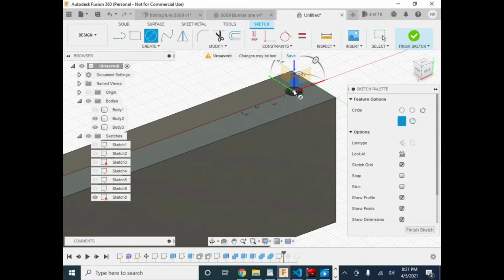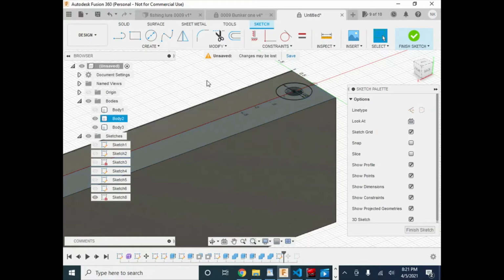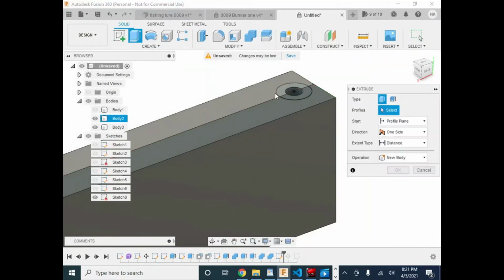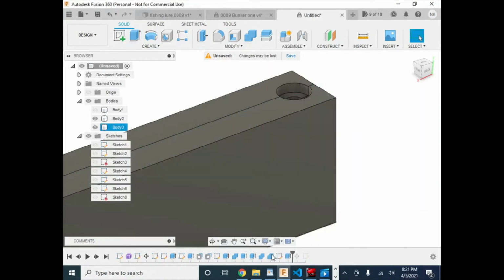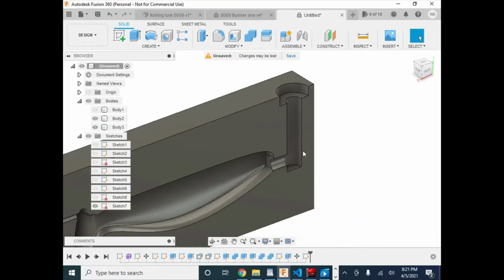We'll pick the center of the hole, and let's say we have a 1-inch diameter port. That's where I would do this operation. It's just easier to remember. And then we'll finish sketch. Extrude it. Click on here. Come down 0.3 just for the sake, and we'll say cut. Click OK, and we'll scoot over to the right.